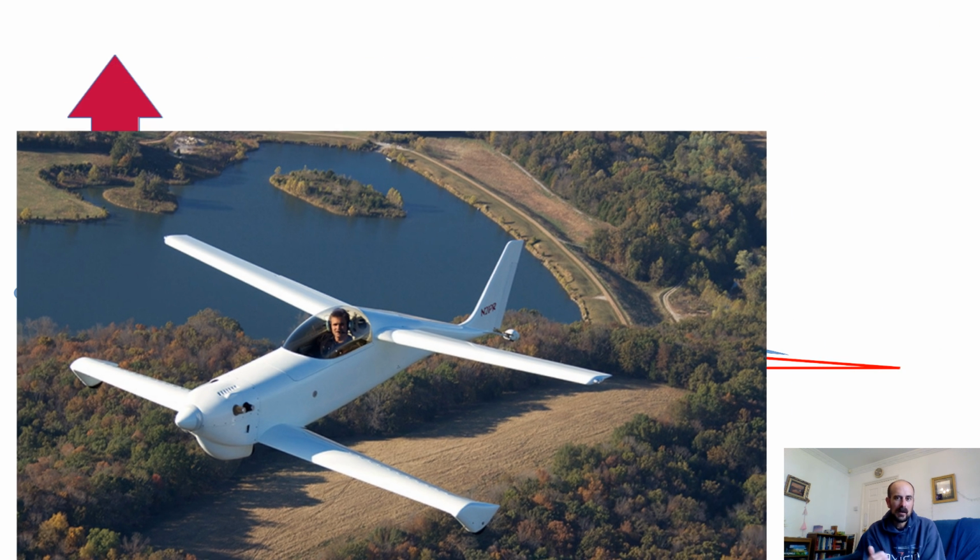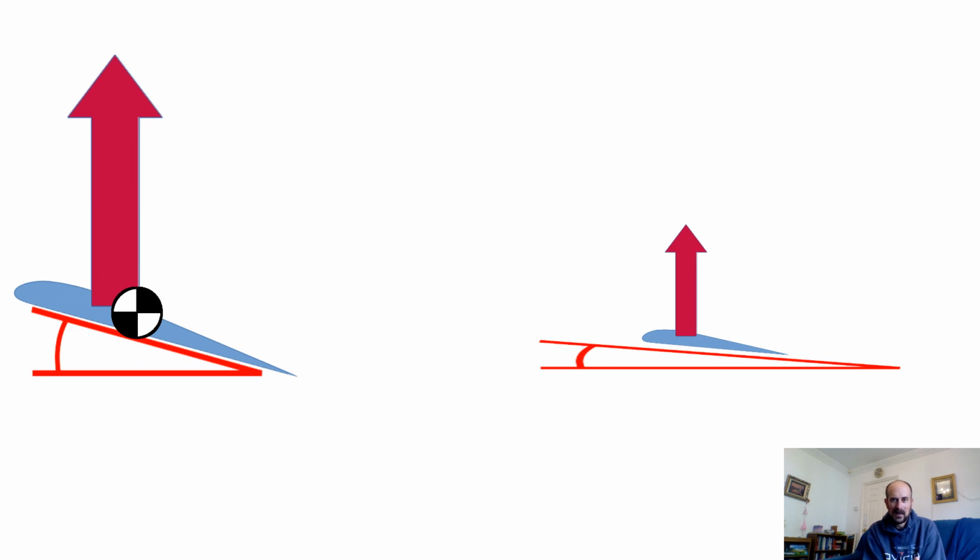So for conventional aircraft, the optimum really is a conventional tailplane, and so you try and make the main wing as efficient as it can be, which means it's as large as it can be, and then you add a tailplane to that, and you're probably aiming for the tailplane to be not lifting or pushing up or pushing down at the design condition.